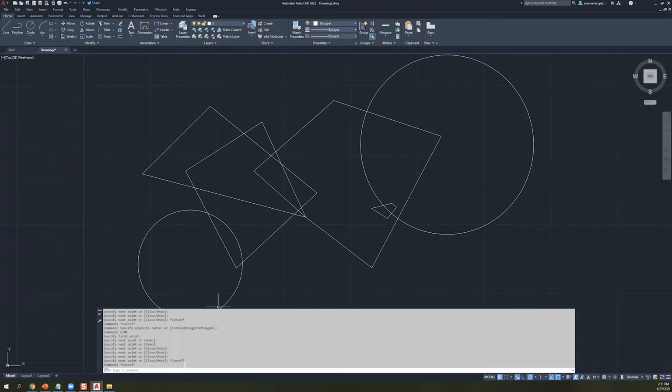Great. It gets a bit more interesting depending on what command you use, of course. My example at the beginning is always to talk about zoom in particular. So type in zoom, and click Enter. Notice you haven't zoomed yet, which is great and all, but in reality, Zoom is actually asking you for a bit more information over here. And so right now it's based in real time.